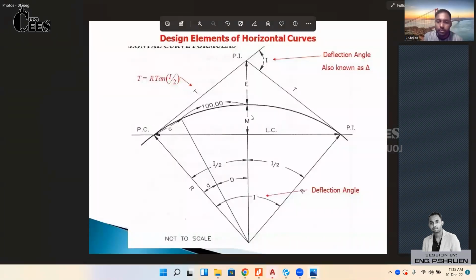I think you see my picture now. In this picture, you can see between the two tangents, we are going to create a curve to make the connectivity to this line. So the start point, if you have studied the highway design engineering subject, then you will know about this picture and know these terms. The first one is point of curvature. At this point, if the curve started here, that point is called point of curvature. This point is called point of intersection.